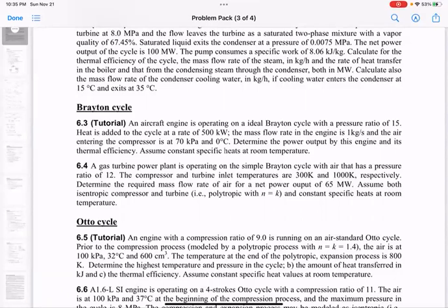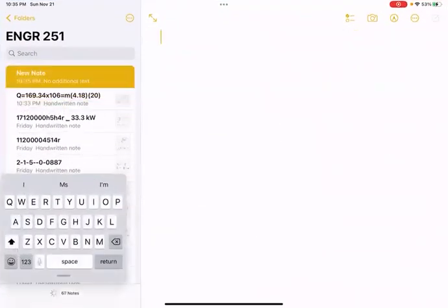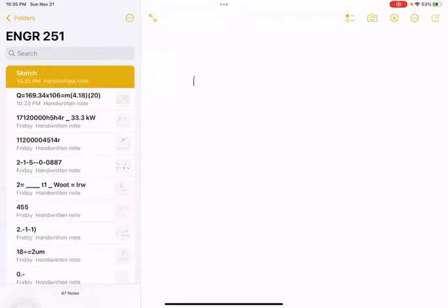Okay, so let's just have a brief look at what the Brayton cycle looks like, since we just did the Rankine cycle. The Brayton cycle is very similar in some ways to the Rankine cycle in that we have an isentropic compression. In this case, the compression process happens in the compressor of the jet engine. So that's the big spinny thing you see at the front, kind of. It's part of it anyway.